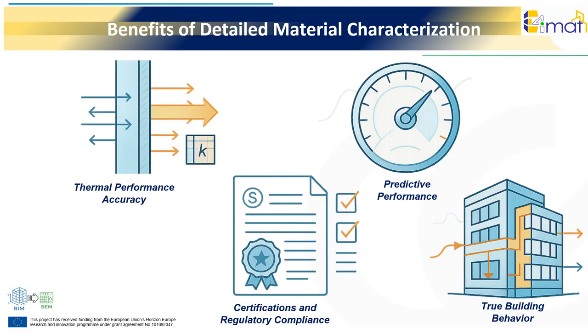One major advantage is the improvement in predictive performance. With precise thermal conductivity, density, heat capacity, and thickness values, the energy model can better estimate heating and cooling loads, temperature stability, and overall energy demand. This reduces uncertainty and increases confidence in the simulation results.